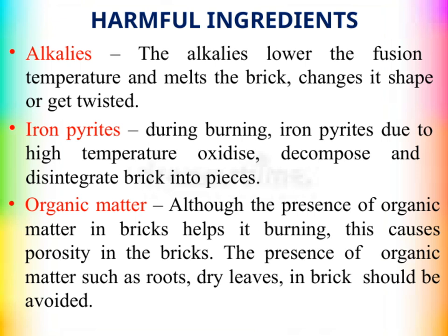So, in summary, these ingredients, alkalis, iron pyrites, and organic matter, are all harmful because they can compromise the structural integrity and longevity of bricks. That's why controlling their presence during manufacturing is essential for producing high-quality bricks.